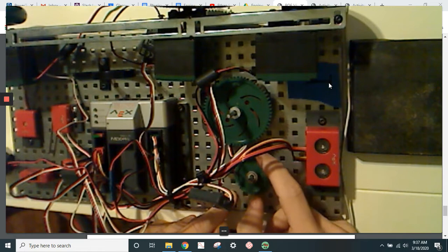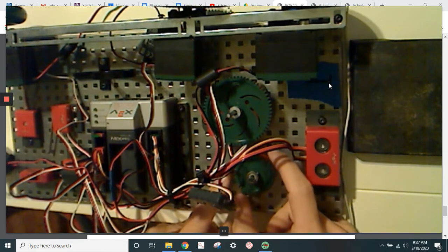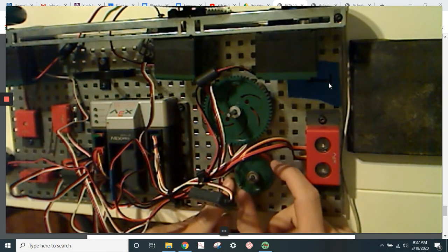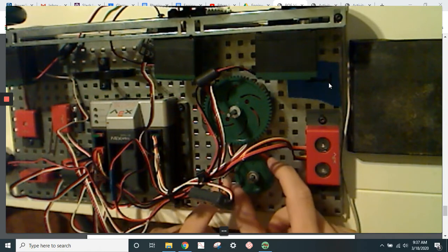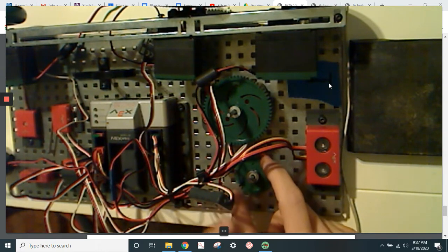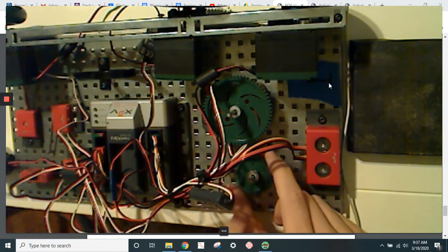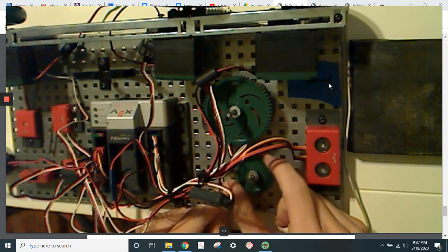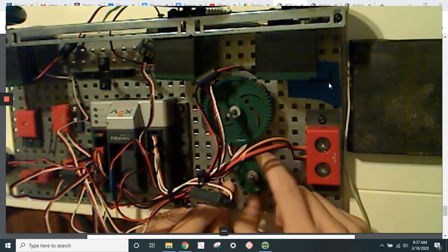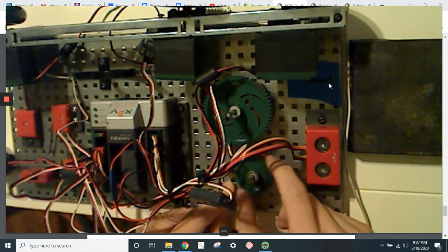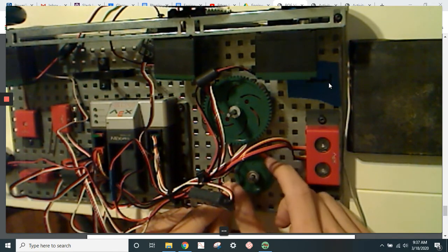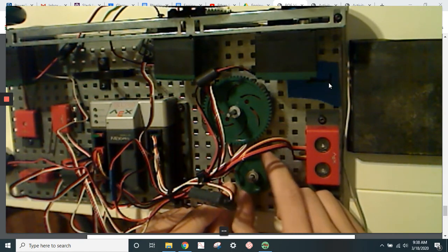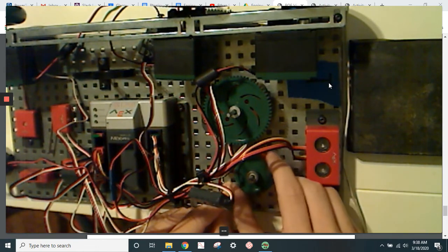The way this works is it's a variable resistor. It has a wire that goes to my cortex that tells me how far it's turned, how much resistance this little device has, because it sends a signal in from here, and then it has a certain amount of resistance, and so a certain current comes back. The robot can pick that up, and it'll give me a value that it's set at. This is useful because I could use this to control the speed of my motor. I could tie that to this. And if this thing's turned, if it's sensing a certain position, then it can respond to that.